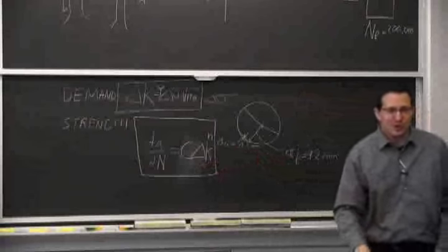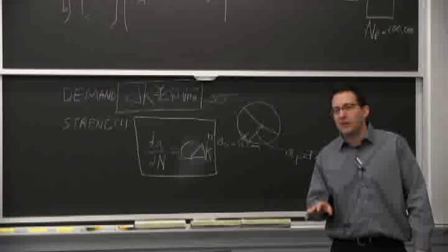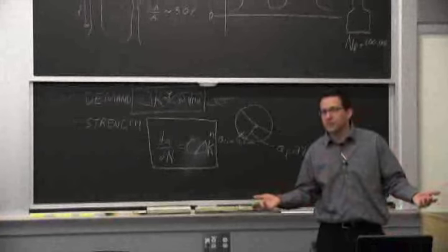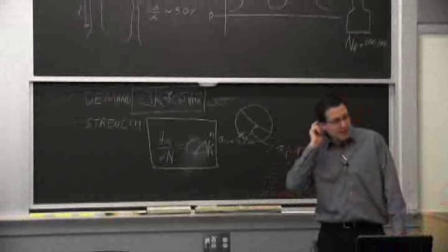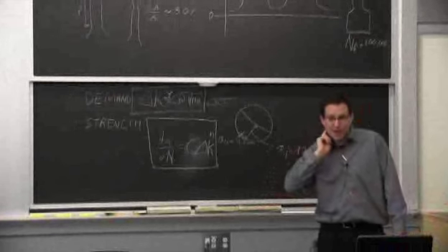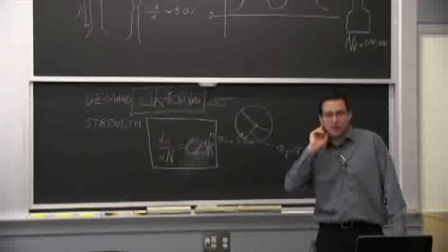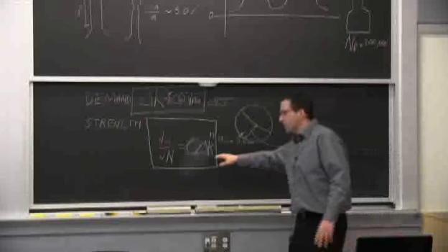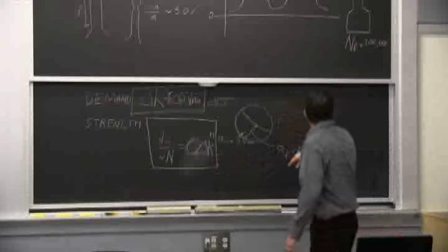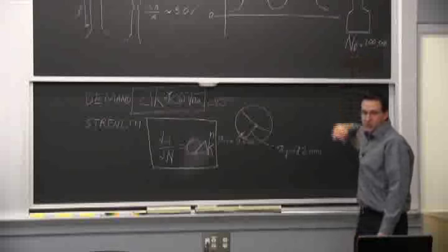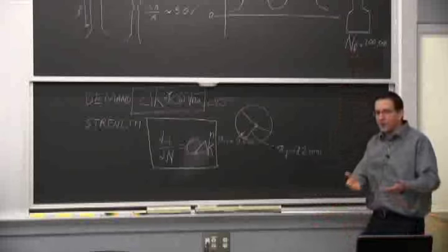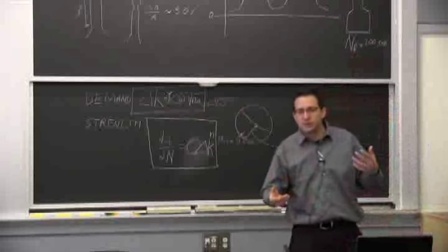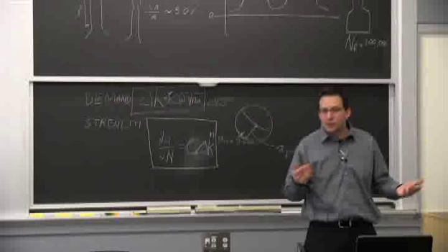And sometimes you don't know, all right? So we'll be fair. You don't know if it's going to be just tension compression, so you look at both. And in the aircraft industry, it happens a lot. So we'll design a part both using what we're talking about here with the stress intensity, and we will also do it this way for the same part, just as an additional tool to evaluate different options.